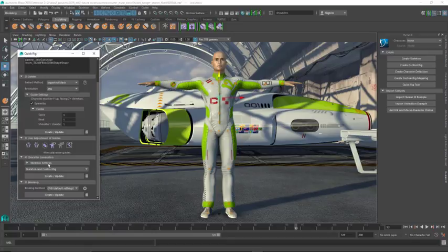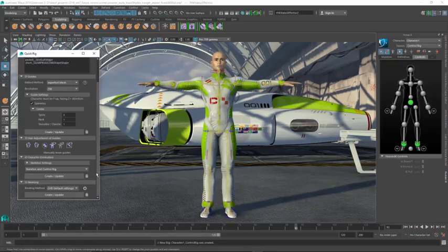So when we make the skeleton, we have a couple of choices. Do we want to have a skeleton, or do we want to have a skeleton and a rig? And the control rig basically means put the human IK solver on there. So this is a solver that has the ability to solve the whole body. It's a full body human IK solver that's basically been around for a while. It's the solver that was inside of Motion Builder. It's an awesome solver if you're trying to animate characters or do anything with motion capture. So we're going to leave that control rig turned on, and we'll have it go ahead and generate that for us now. So you can see Maya goes through, it makes the joints for us, and it makes this really nice control rig.